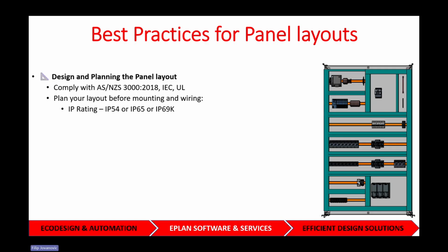So first, one big thing is when you're choosing your panel, you need to consider the IP rating. And that's going to be affected by where your panel is placed. Is this panel going to be placed indoors? Is it going to be placed outdoors? Will it be in a dry environment? That will determine your water safety, dust protection level, or IP.